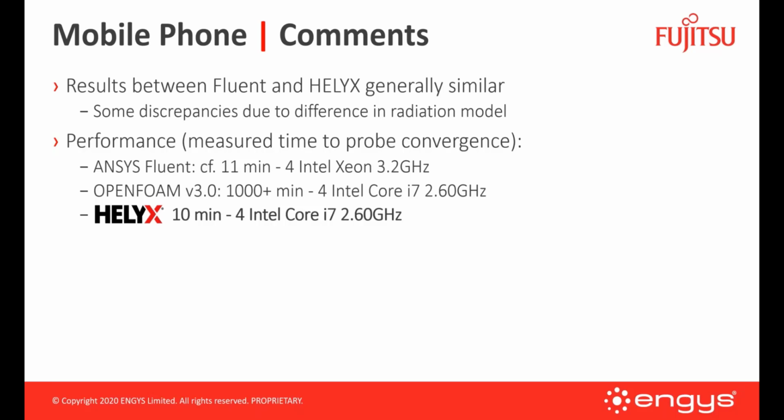The performance measured, the convergence, was a measure of how fast the probe temperatures converged. For Fluent, this took about 11 minutes on 4 Intel Xeon processors. For OpenFOAM, it took greater than 1,000 minutes. And for HELYX on 4 Intel Core i7s, it took about 10 minutes to converge.